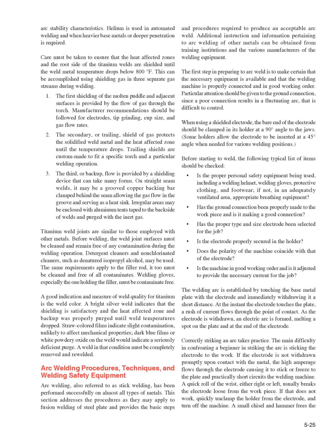Titanium weld joints are similar to those employed with other metals. Before welding, the weld joint surfaces must be cleaned and remain free of any contamination during the welding operation. Detergent cleaners and non-chlorinated cleaners, such as denatured isopropyl alcohol, may be used. The same requirements apply to the filler rod; it too must be cleaned and free of all contaminants. Welding gloves, especially the one holding the filler, must be contaminant-free.